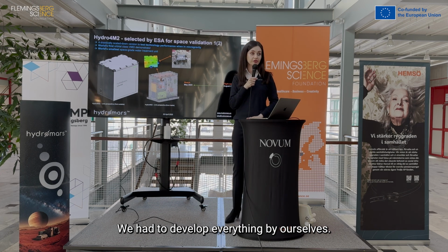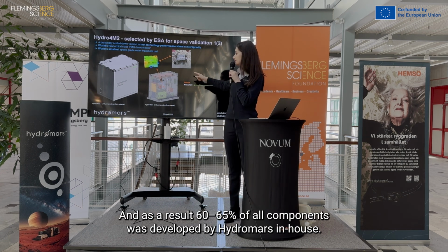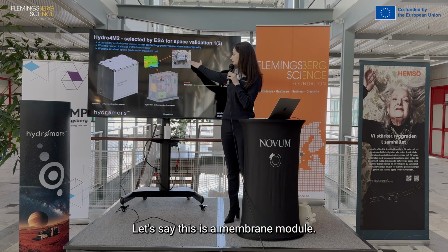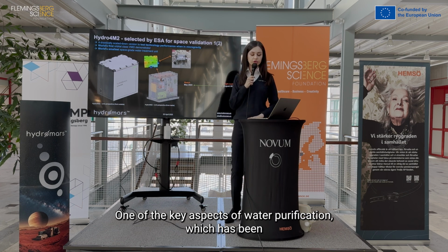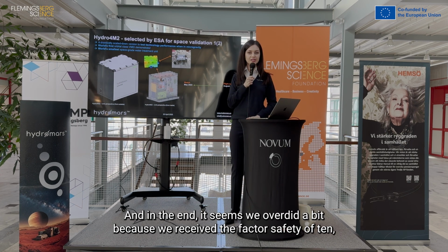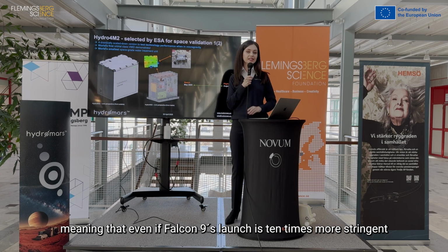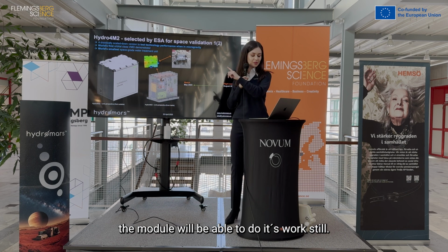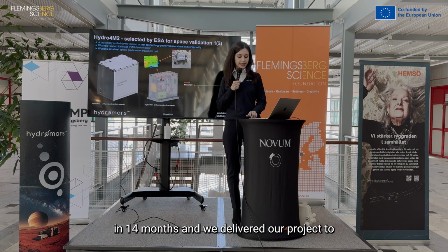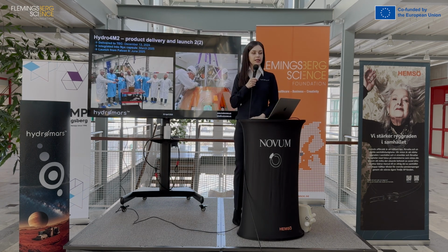We had to develop everything by ourselves, and as a result, 60-65% of all components was developed by Hydromars in-house. Let's say this is the membrane module, one of the key aspects of water purification, which has been structured, designed, and developed by us, and in the end it seems we overdid a bit because we received a factor of safety of 10, meaning that even if Falcon 9's launch is 10 times more stringent, the module will still be able to do its work.